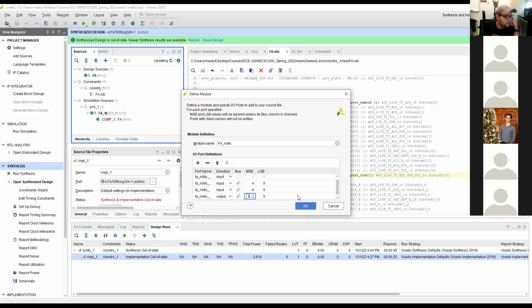Anyway, so they're gonna be output and they're gonna be 4 bit also, right? I mean 5 bit. Then we're gonna make another one here, which is basically if A in bits, and they're gonna be port sum, and they're gonna be if A in bits, right? Port carry out, and that will be how many bits? Normal carry out for multi bits is what? Just 1 bit, exactly.